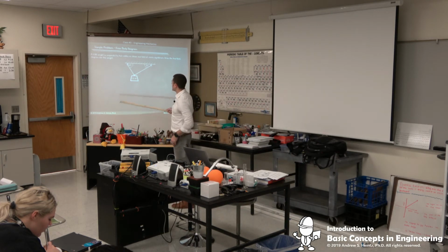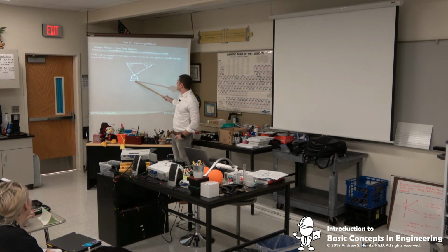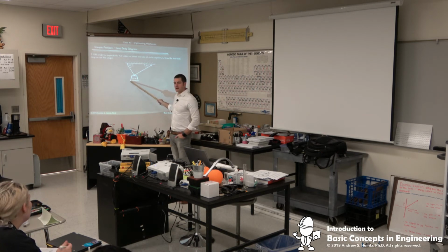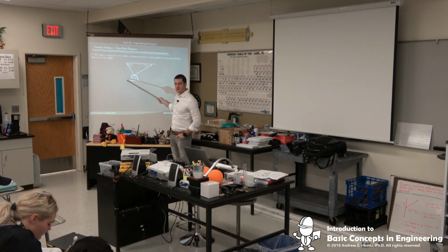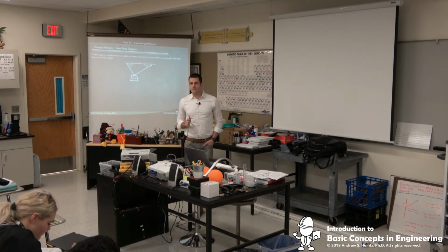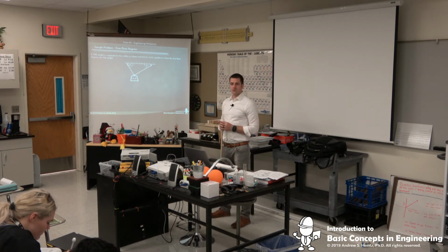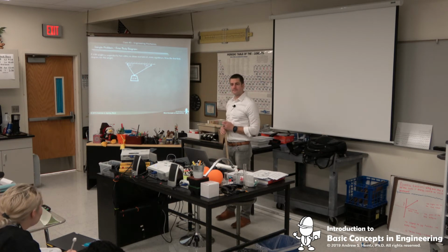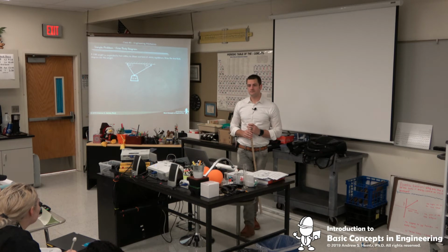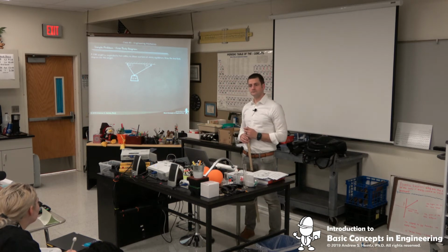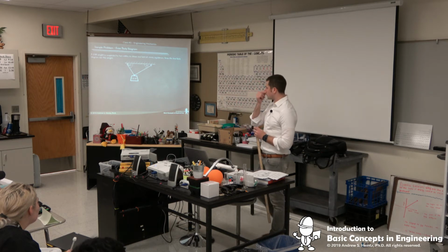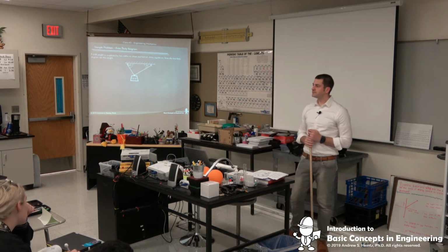We have a 20 Newton weight suspended by 2 cables. So what I want you guys to do is draw the free body diagram for this weight. We don't have to solve anything yet, but what I care about is what's happening to this weight. So let's talk about this together. Chandler, what's one force acting on that 20 Newton weight? Gravity, perfect. So how are we going to draw that? I would draw a line underneath the 20 Newton weight pointing down. Okay, perfect.